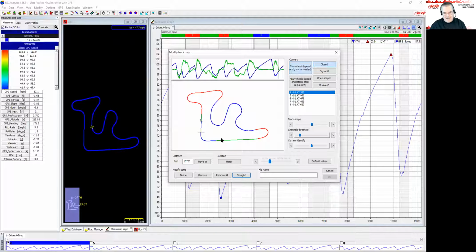We spent some time there, but what we did is I walked around the track the way that you might want to for your style of track map that you're after, right? And we use this bar across the top, these little strip charts, to understand and stay away from transition areas, so our split reports will be very, very consistent. Our theoreticals and our best rolling laps, all of that will be a much better representation of what is happening because we stay away from those transitions.